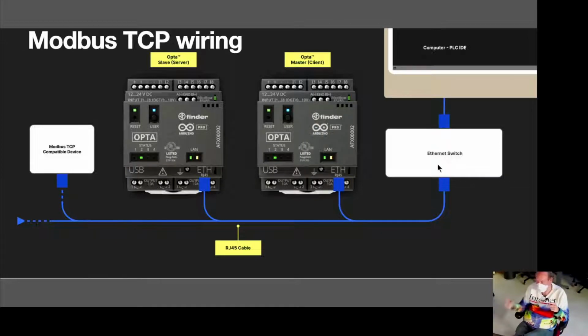Additionally, having your device act as a Modbus server is the way industrial HMIs are presently done, or the old way they're done. So you would define Modbus addresses in your PLC code, and then your HMI would read and write to those for showing buttons on screen or readouts or temperatures or whatever.